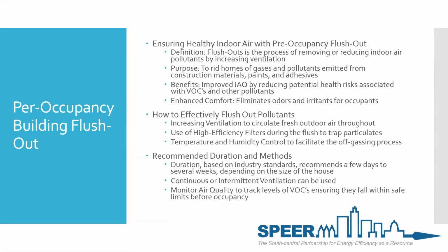Another one is pre-occupancy building flushouts. This is not required by code, but it's an above code program. Like for LEED, it's a requirement. So there has to be a certain amount of time given to pre-flush the house, or have a flush out. So opening all the windows and doors and leaving it that way for 24 hours, letting things off gas and letting that contamination exit the building itself. By methodically removing or significantly reducing indoor air pollutants through this process, you set a good foundation for a healthier indoor environment from day one. This practice not only demonstrates the commitment to indoor occupant health, but it also underscores the importance of considering air quality in every phase of the construction.